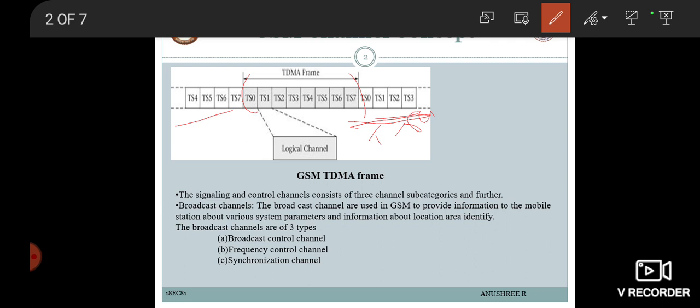The time slots can be considered logical channels. That is, from a system point of view, each time slot may carry either subscriber traffic, or it can also carry signaling and control information which is required for the management of the radio link and other system resources. The system can use several different types of repeating frame structures, known as multi-frame, depending upon the type of information being transmitted.